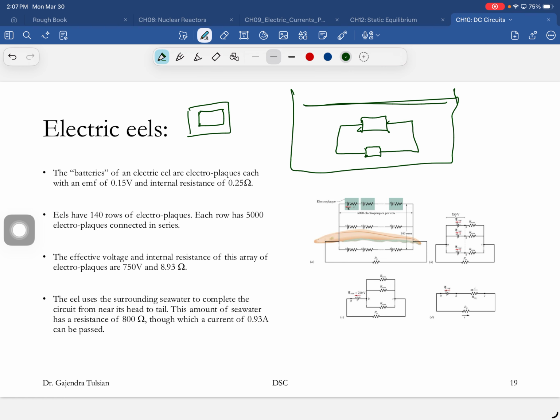Okay, so here's another device. You guys might have seen these three-way lamps, which will have two filaments. When you close this switch, it acts like a 75-watt bulb. And then you open this switch and close this switch, and it'll act like a 100-watt bulb. And then when you close both the switches, it acts like a 175-watt bulb.